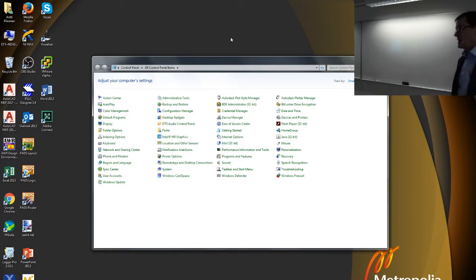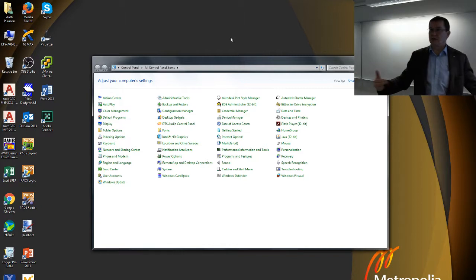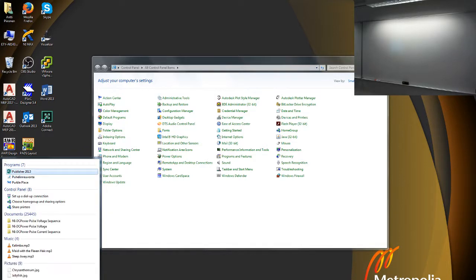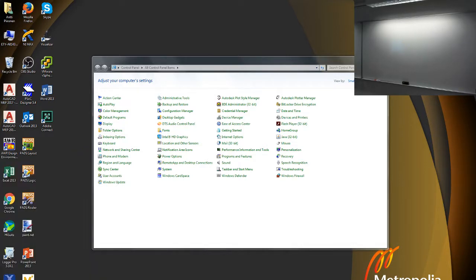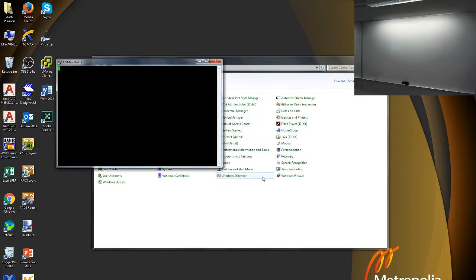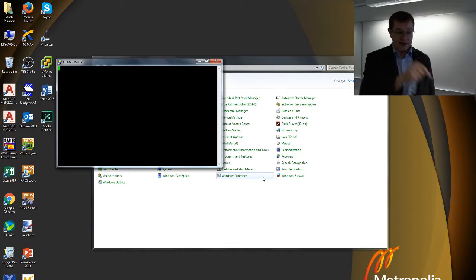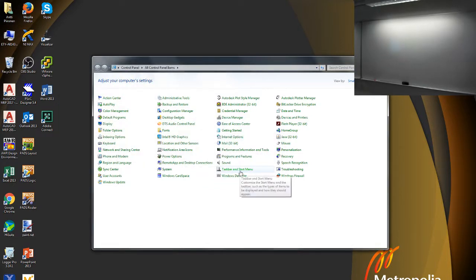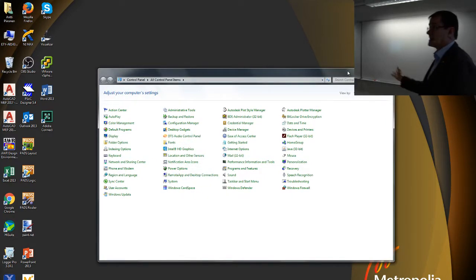Okay, and how to then see what happens on the COM port? The easiest program would be PuTTY. And there, just serial port COM9, open. Now this is connected directly to that device, and it shows whatever data is transmitted through this bridge. So that's the easiest way of testing your data transmission. How to then save that data, well, that's another course.